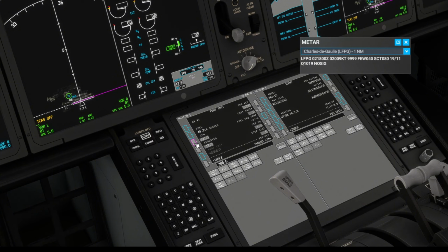So if we take our zero fuel weight, 388.6 plus our fuel equals a gross weight of 437.8. So that is in accordance with my flight plan. And the flight plan basically tells me 434.6, but we added some extra fuel, so it looks absolutely fine since we put 3.2 on top of it.